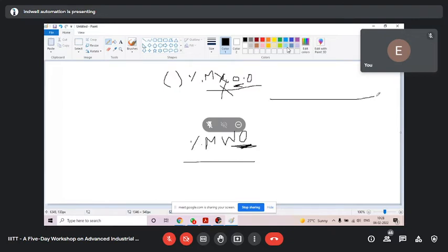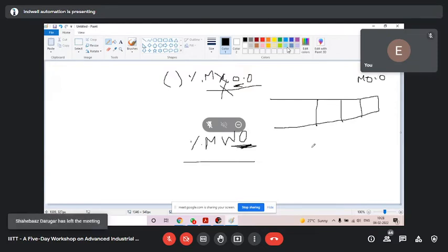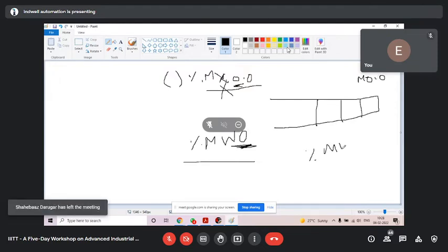What will happen if you have used M0.0 in your program and you use %MW0 also in your program? You had taken time to word, so it was getting some numerical value, 1, 2, 3, 4. So as it gets the decimal value 1, what will happen, you know? What is the binary of 1? Tell me.